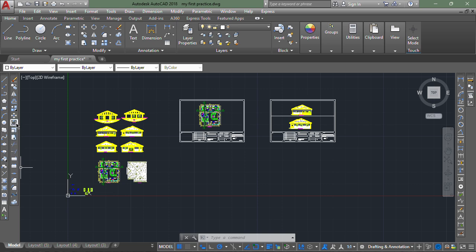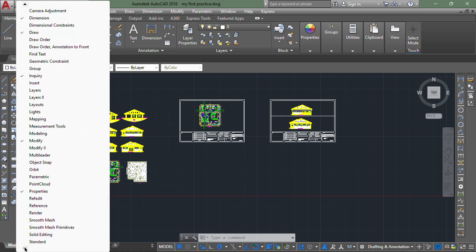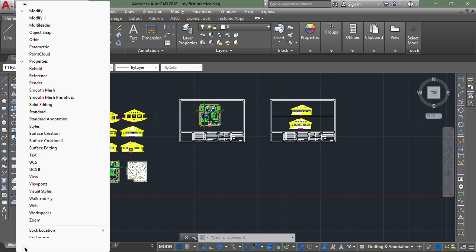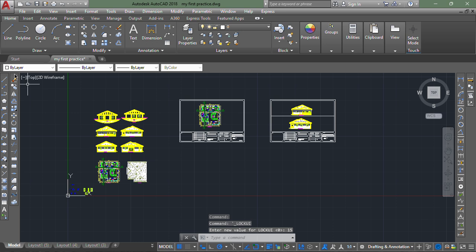And by doing that, you can just right click, like as if you want to bring out another tool section, and come down to the last part here. Now you're seeing Lock Location, then you can come here and lock everything. So no matter how it is being dragged, it will not be able to move, right? So at least you rest assured that there is no accidentally moving the object. Here also the same thing, it will not be able to be edited. So it is just locked like that, right? And you are good to go.